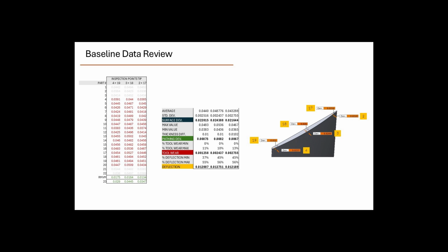That's the reference. For control point number 2 and control point number 17, the total deviation is added. What our inspection software does is it takes the CAD surface at that point and shoots off normals from that particular point in either direction. Whenever it hits the measured data points, it will give you a positive or negative deviation. If the surface is inside the CAD, it will give you a negative. If it's outside the CAD, it will give you a positive. Again, that red to blue color plot.